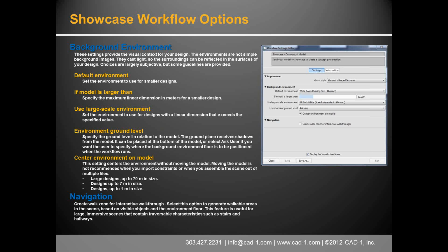So we've got where's the ground level that we have to specify. In my model, the 100 feet is where the ground plane's at. So if I were to import this in and not change it, it'd come in at 0, and you'd see my building way up at 100 feet in the sky. So if you're building this in your site plan, and you've got your model out there at 8,250 feet, and you bring it in, you're like, where's my building? It's nowhere. I can't find it. This thing doesn't work. What's going on?